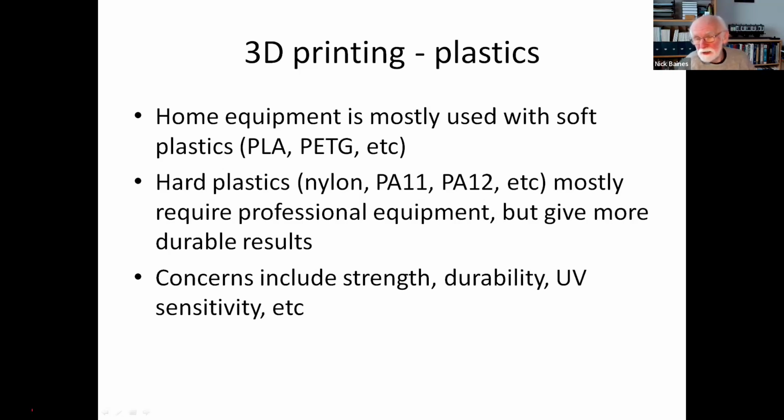Also, things like UV sensitivity. If I leave it out in sunshine for a long time, is it going to either deform or degrade, become embrittled, something like that? I think there are some significant downsides. I know people do use them. I use them myself, but you have to be aware of the issues there.